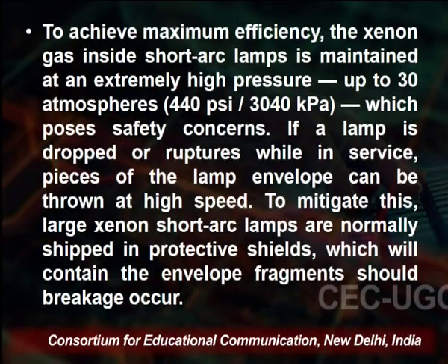In low power applications, the electrodes are too cold for efficient electron emission and are not cooled. And in high power applications, an additional water cooling circuit for each electrode is necessary. To reduce the cost, water circuits are often not separated and the water needs to be deionized to make it electrically non-conductive, which lets the quartz or some laser media dissolve into the water. So, normally we are having the maximum efficiency.